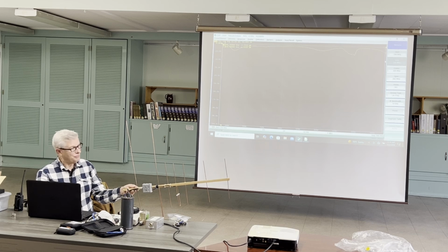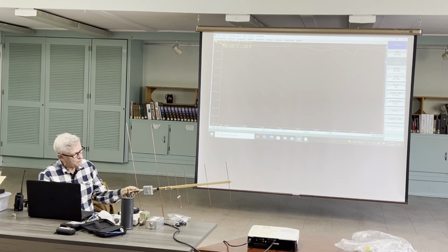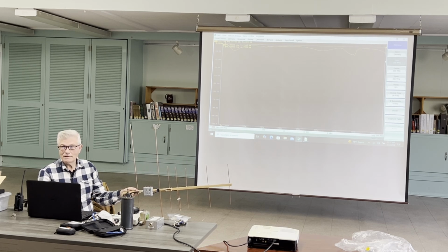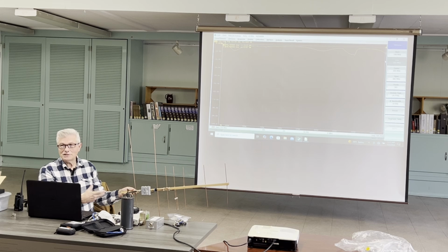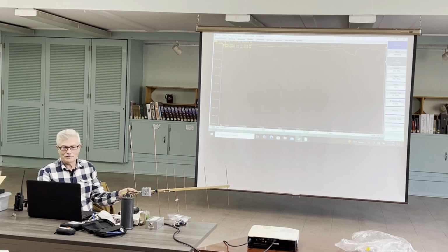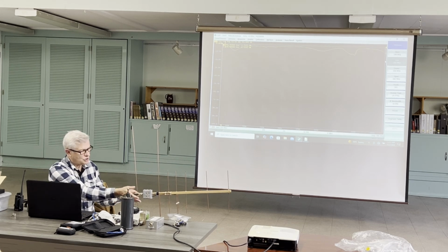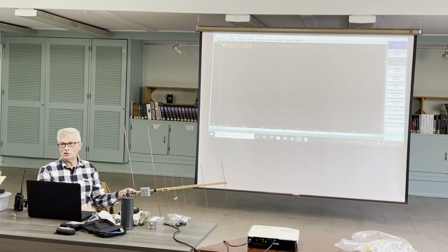And I got to tell you something. The way to probably fix this, you're going to think this is crazy, but your component values are probably okay. Did you wind your own coils for this? Yeah. Stretching the coils is the first thing you want to start with. You would take this apart and you would mess with it. Now, of course, as soon as you put the cover back on the box, it's going to change. So work in progress. Yeah.